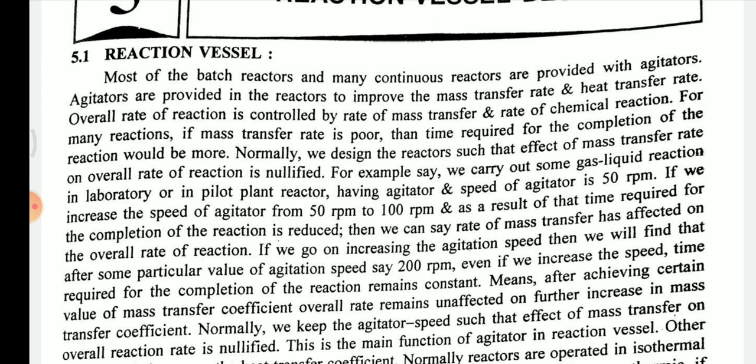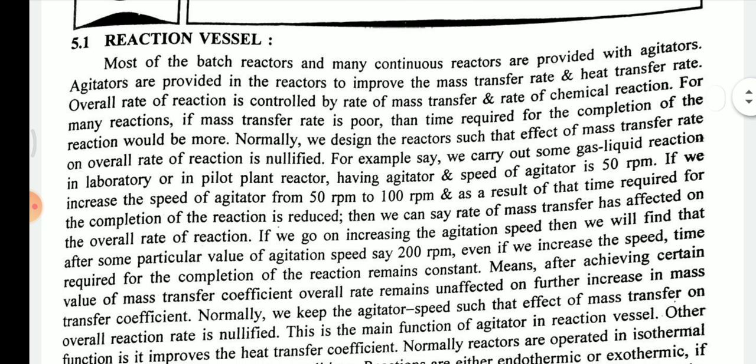Basically it is used for mass transfer and heat transfer. It is helpful to the overall reactions. It is doing mixing, which is the mass transfer rate, and it will be applying heat transfer as well. So the overall rate of reaction is controlled by the rate of mass transfer and the rate of chemical reactions.